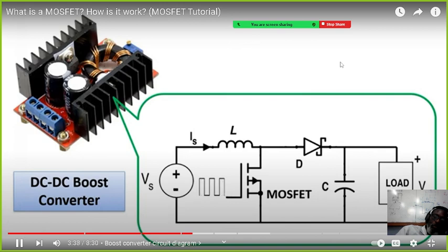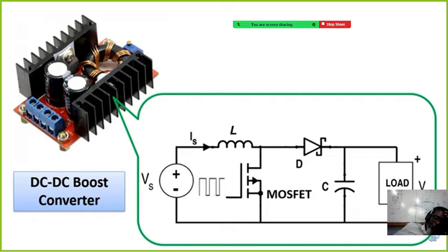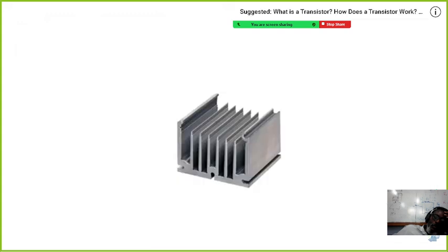With the MOSFET located here, triggers are made at high frequency values at the kilohertz level. In this way, MOSFETs and Schottky diodes are preferred in order to obtain healthier results, instead of using normal silicon diodes, in order to respond to high-frequency switching speeds in converter circuits. DC to DC converters and motor drivers using MOSFETs naturally get hot because very high current flows through them. As such, they need coolers.